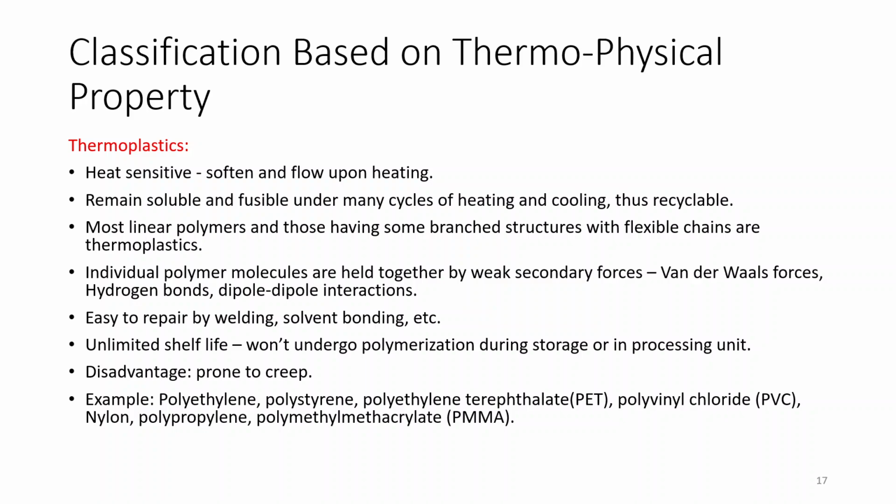The individual polymer molecules are held together by weak secondary forces such as van der Waals forces, hydrogen bonds, and dipole-dipole interaction, and these bonds are easy to repair by welding. These thermoplastics can be easily repaired by welding or solvent bonding, etc. And these have unlimited shelf life as they won't undergo polymerization during storage or in the processing unit. One of the disadvantages is that these are prone to creep, so they can't be used at higher surface temperatures.